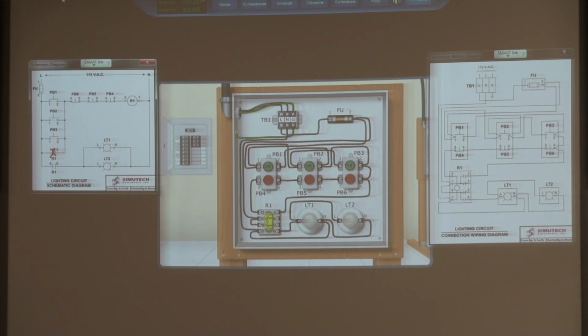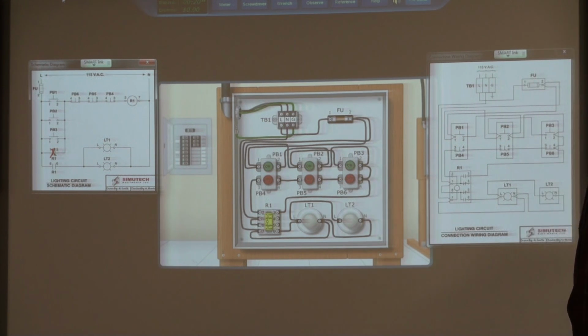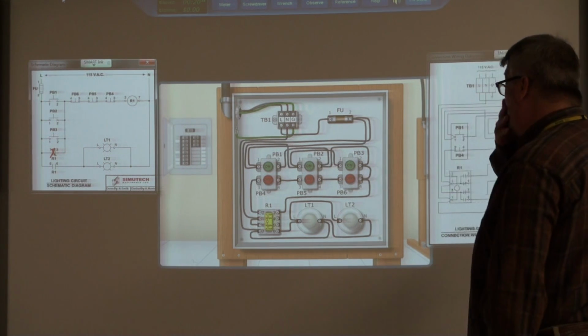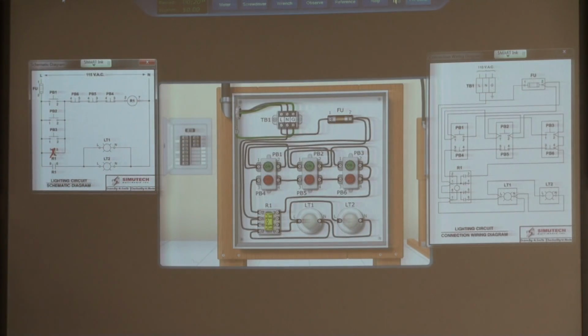We could press PB1, and the lights would come on until we let go of PB1. We could press PB2, the same thing would happen. We could press PB3, and that's simply because it's the inverse of what we had before. The lights are going to cut on when the relay coil engages. What's supposed to happen is both contacts change state. This one changes state to provide a path for the lights. This one changes state to provide a latch for PB1, PB2, PB3. But it doesn't.